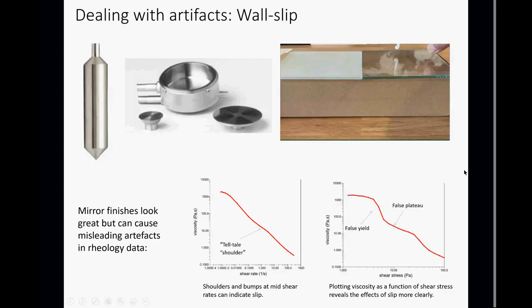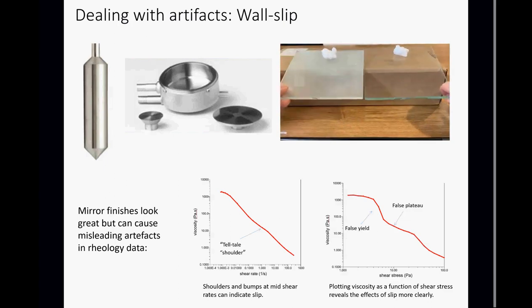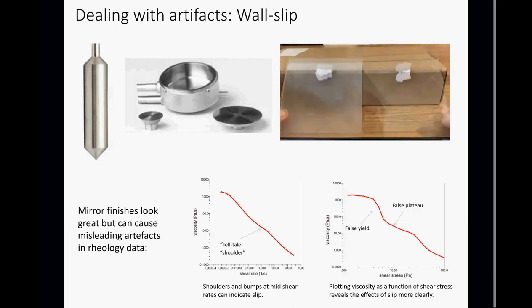One more thing we need to look at is what can cause problems for you when you're taking measurements. Many viscometers and rheometers are provided with some very nice, smooth, shiny surfaces, and that's often the last thing that you want when you're performing rheology testing. In rheology, we want to encourage bulk shearing, and if we have smooth surfaces, that can work against that.